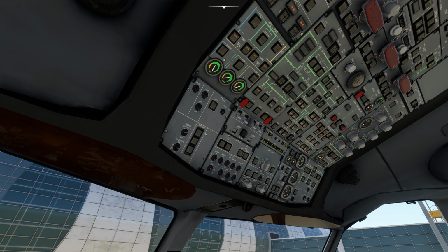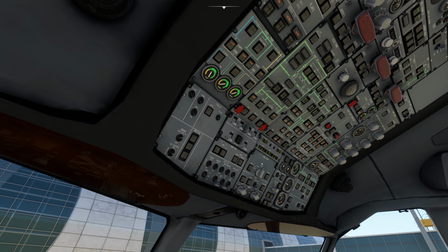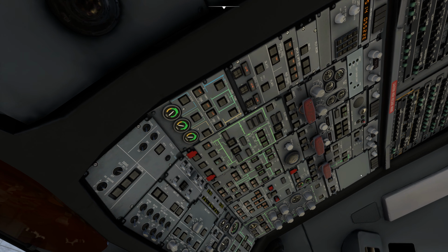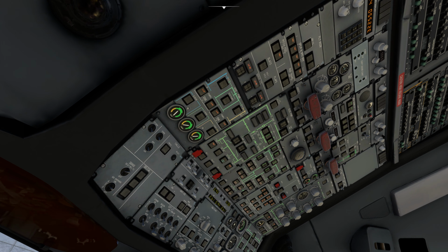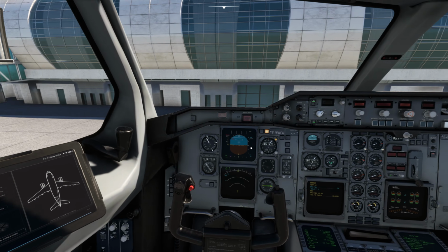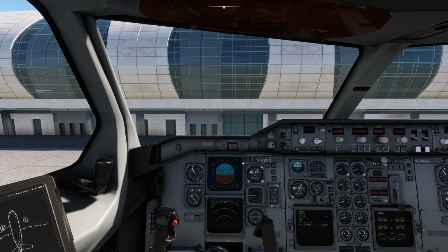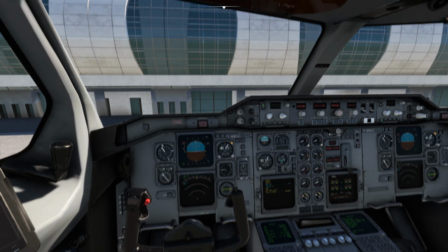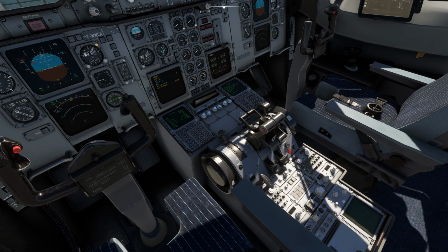The way you got it, just set the plane in such a way, the way you got it. ATS off, auto thrust, and what else? And just do this. And maybe you want to unlock the cockpit door. And that's it. So don't turn off the nav or the ADRS, or if you are going to store the plane, then you have to turn off the ADRS as well. So that's it. Now the plane has the power. Turn off the constraints, you don't need them. Maybe you can turn off the weather radar also.